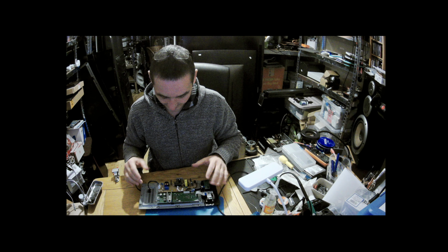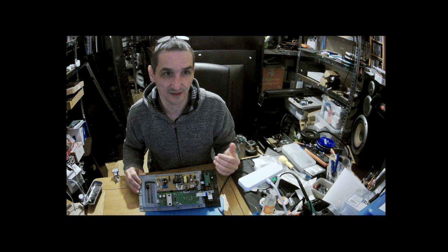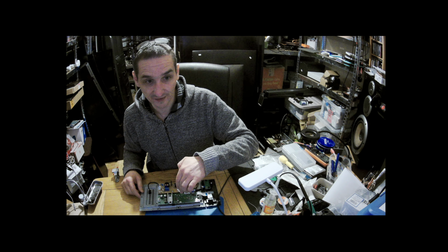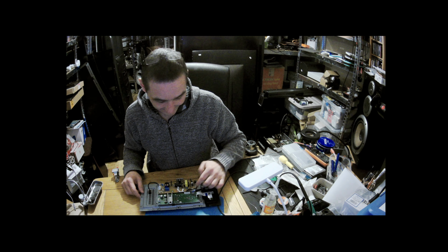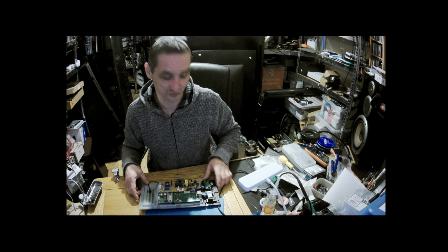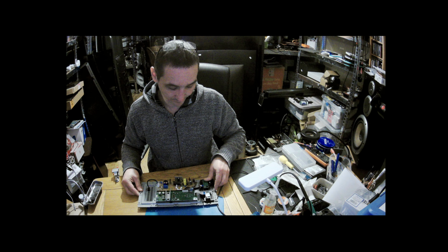fixed board. Yes, so here I've checked and the power supply section works fine. Okay, so we should get 18 to 24 volts, which we have, and this has to go to the sub board, logic board. Okay, now here on the connector to the power, to the main, to the power switch here, okay, we should get 3.3 volts, and we don't.